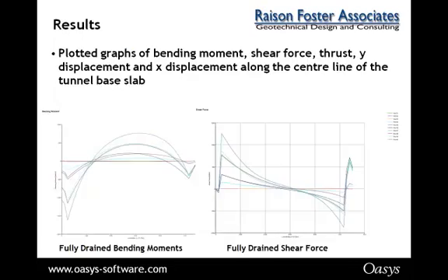And in terms of its outputs, SAFE is able to take various sections through the different problems, but I've just focused on the one here where we've taken sections through the base slab and we've looked at the bending moments and the shear force at different points in the construction stages.